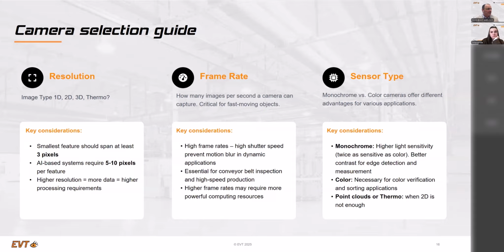If the application needs a gray camera, a color camera doesn't make sense and needs only computational power, especially if you intend to use a not so powerful system like a smart camera. Most smart cameras have these ARM CPUs, but not with a high clock rate like, let's say, smartphones.